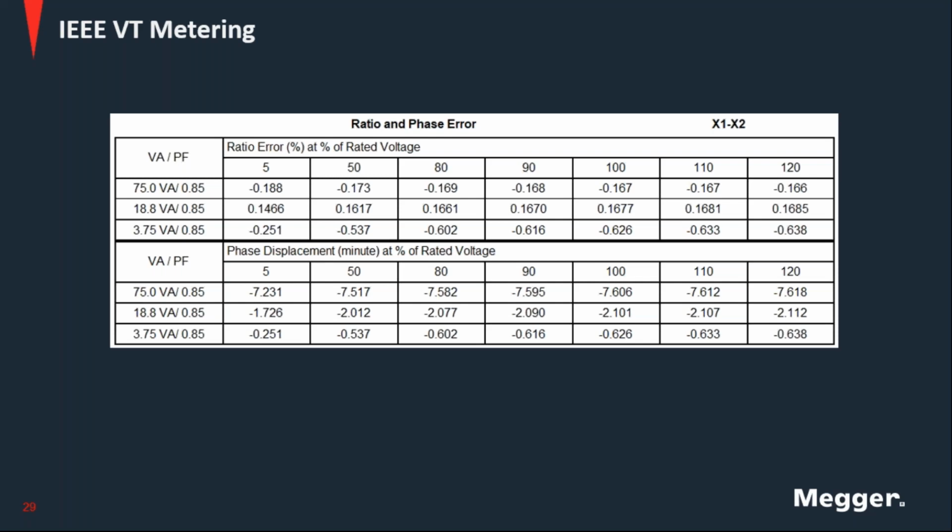In this case, whoever ran this test did not measure the impedance of the circuit connected to the CT. So we don't have the actual evaluation at real burden conditions, but still you can see how linear the behavior is throughout the range of the instrument transformer.